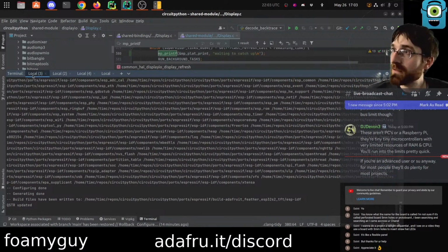Oh yeah. Displayio is good for, honestly, if you're not trying to do motion, if you're not trying to have a thing move necessarily, if you're just trying to pull data from any kind of system and put it on the screen and update it every few minutes or a few seconds, Displayio is more than adequate for that.